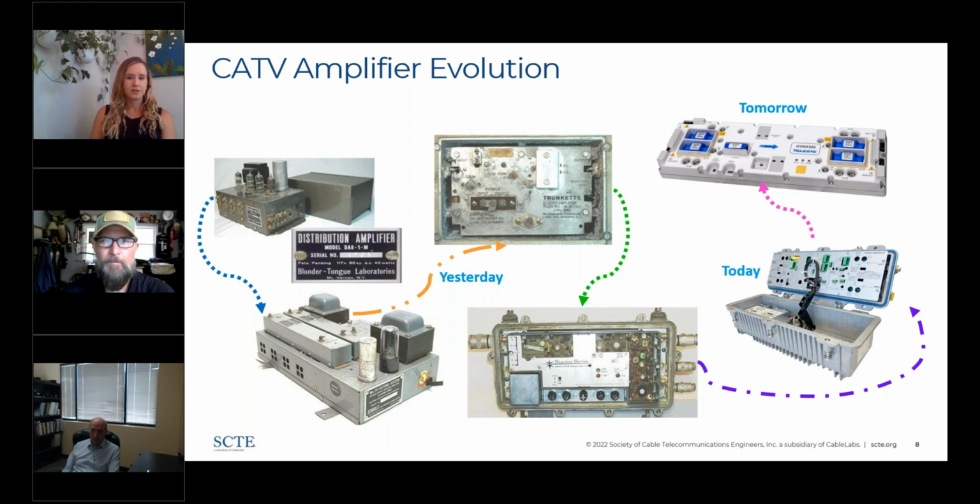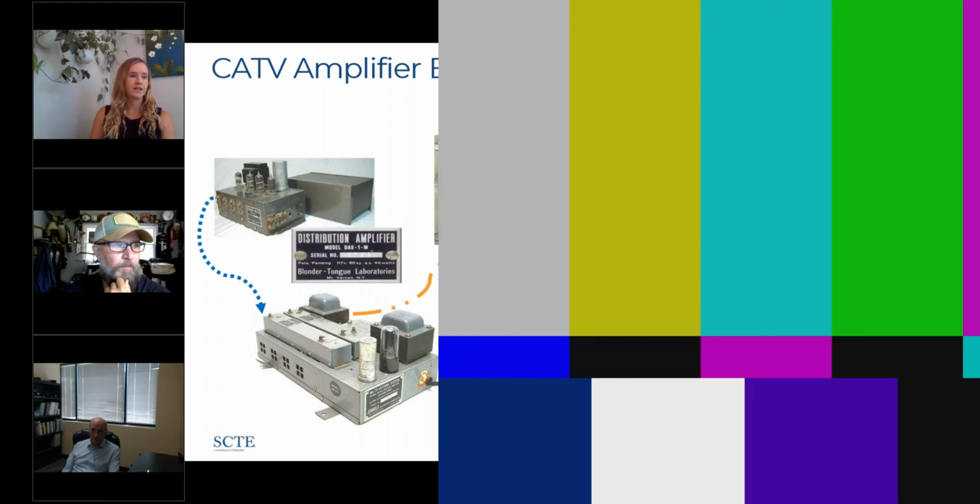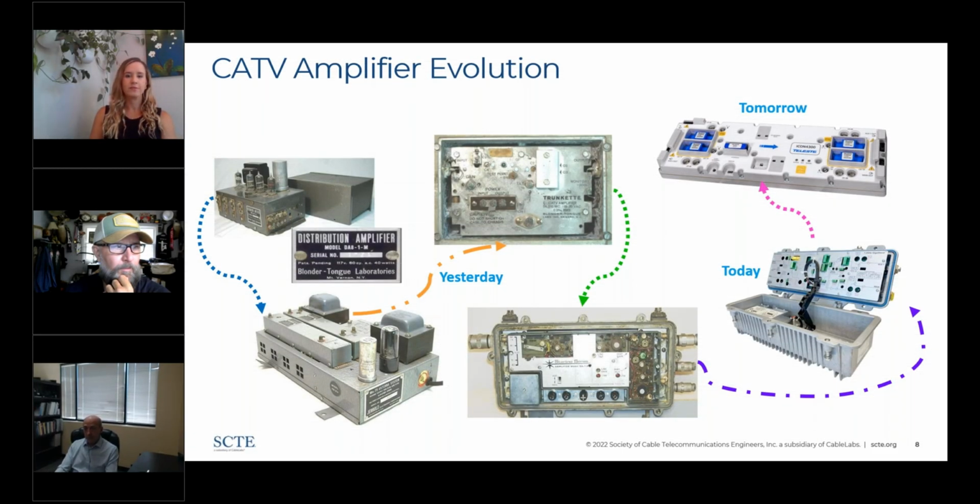This had a really simple circuit, with a bandwidth between 54 and 212 megahertz, and they only supported the downstream direction. By the early 1970s, cable television upgraded those twin lead wire amplifiers to a higher technology called solid state actives. Those were introduced to support higher bandwidths, up to 330 and then 450 megahertz.